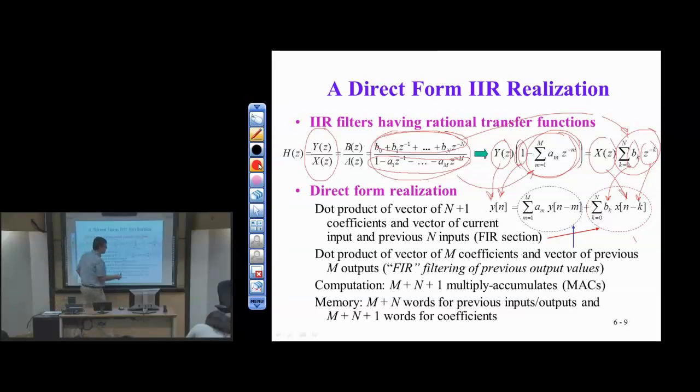And so what is the inverse Z transform here? Well, again, this term is being multiplied by a capital Y of z. So a sub m is a constant with respect to little n, the discrete time index. z to the minus m means I delay by little m. And then finally, the inverse Z transform of capital Y of z is little y of n. So that's my term on the left. Corresponds to the inverse Z transform of this summation times capital Y of z.